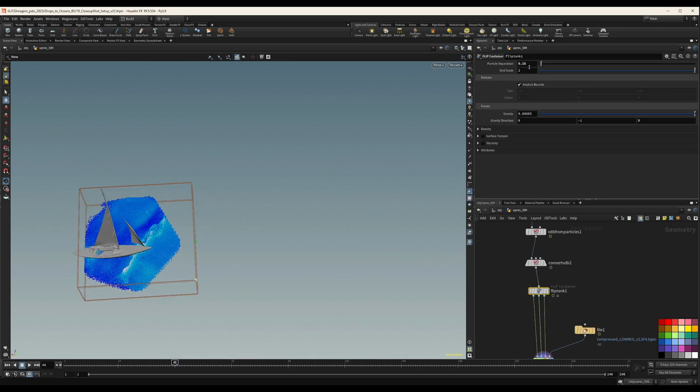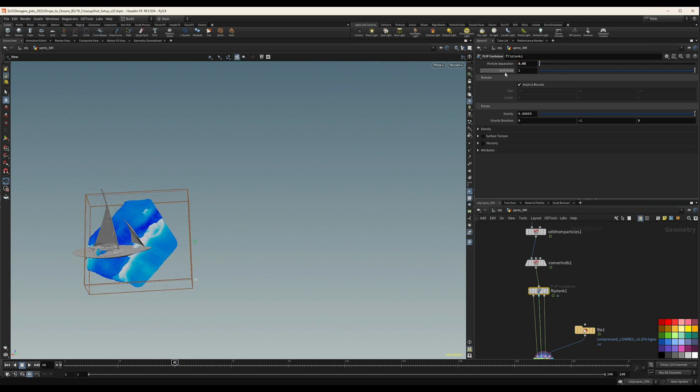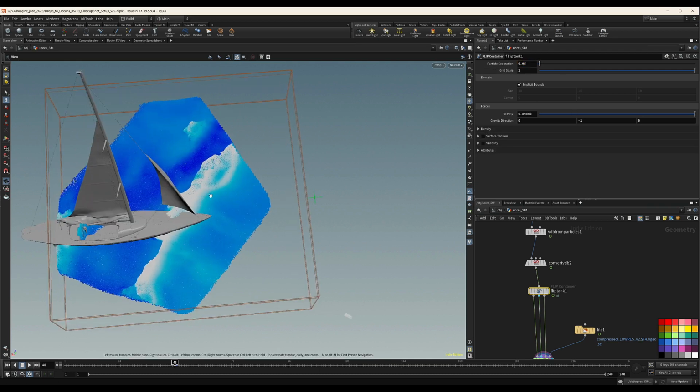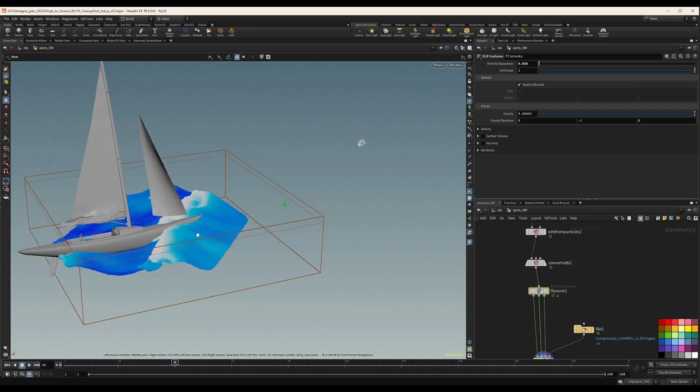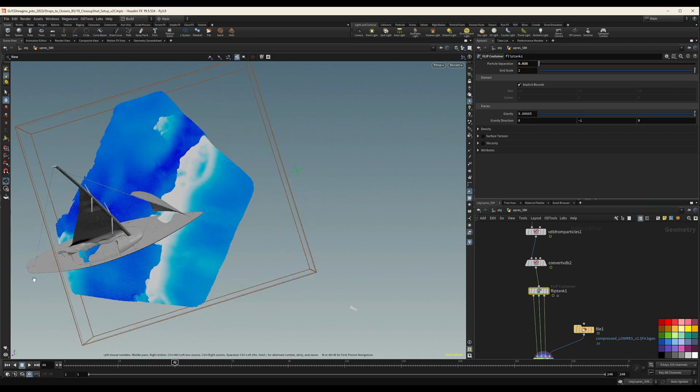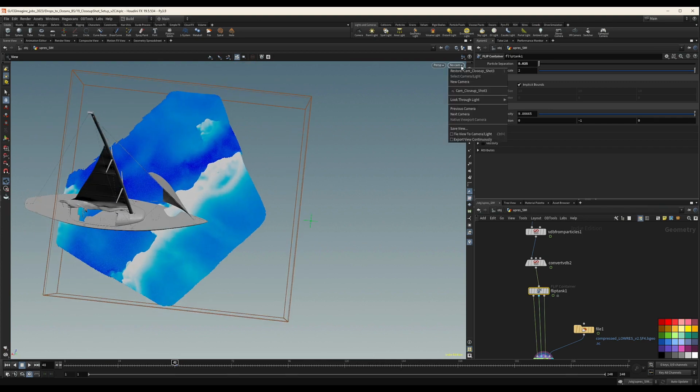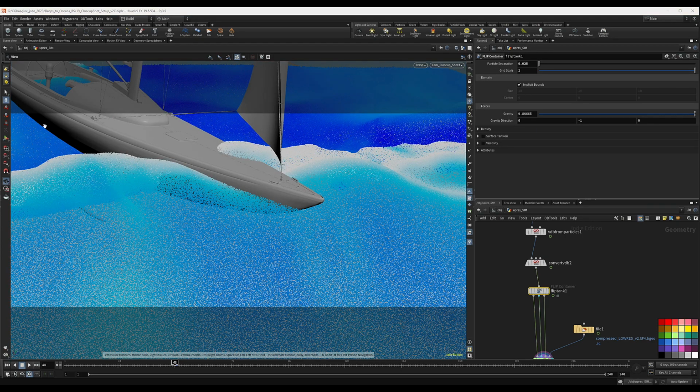And now I can come in here and reduce the particle size to 0.5. I'm going to go even higher, but you see how compact. And this was very low res and I can come in here and do, for example, 2.5 and see how fast, and it's very optimized. And if I look from the camera perspective, it's all covered and with some room outside also.